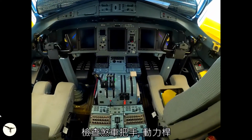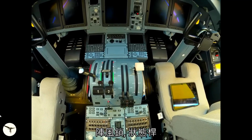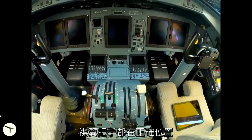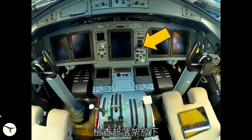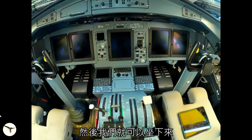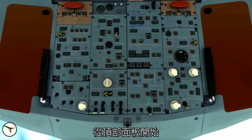On the pedestal, we check that the brake handle, power levers, gust lock, condition levers, and flaps lever are in correct position. On the central instrument panel, we check that the landing gear is down. Then we can sit down and start the full cockpit preparation procedure. We start with the overhead panel.